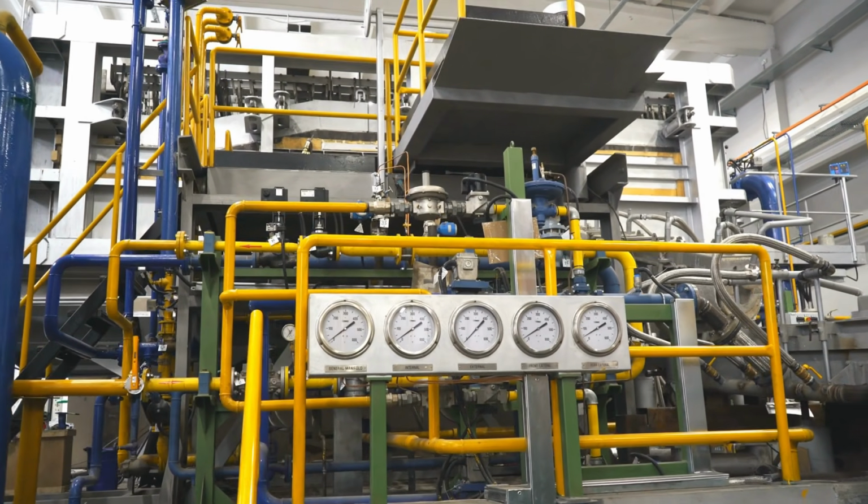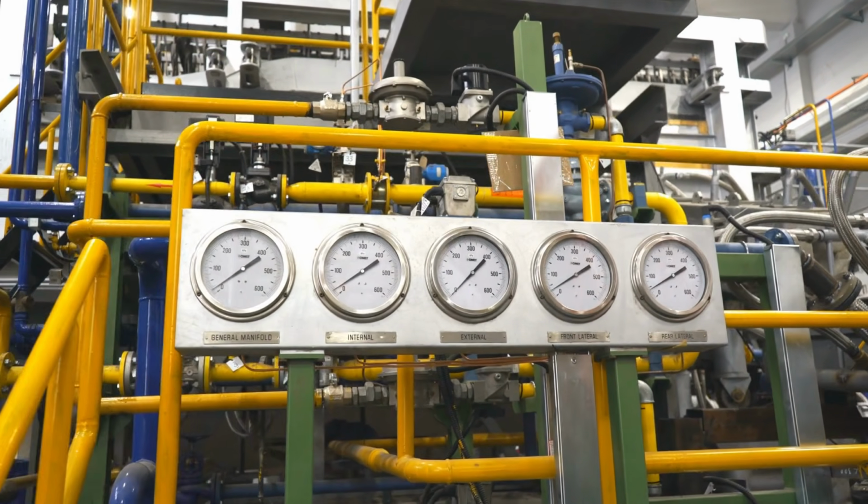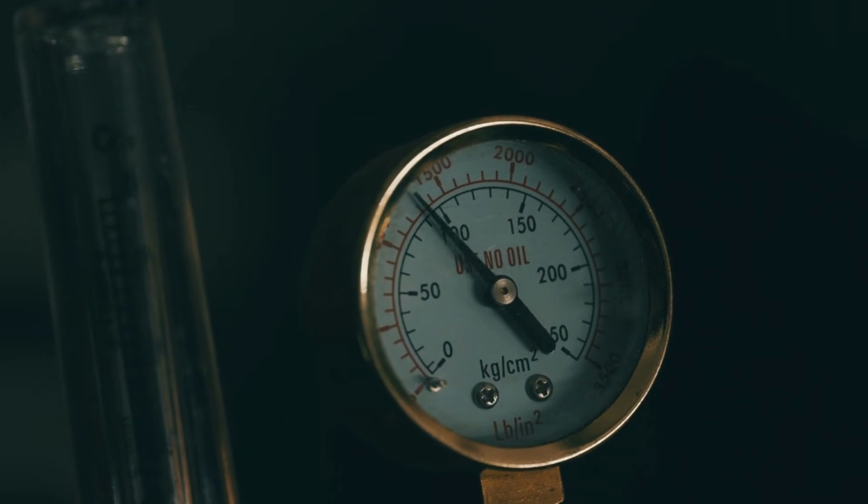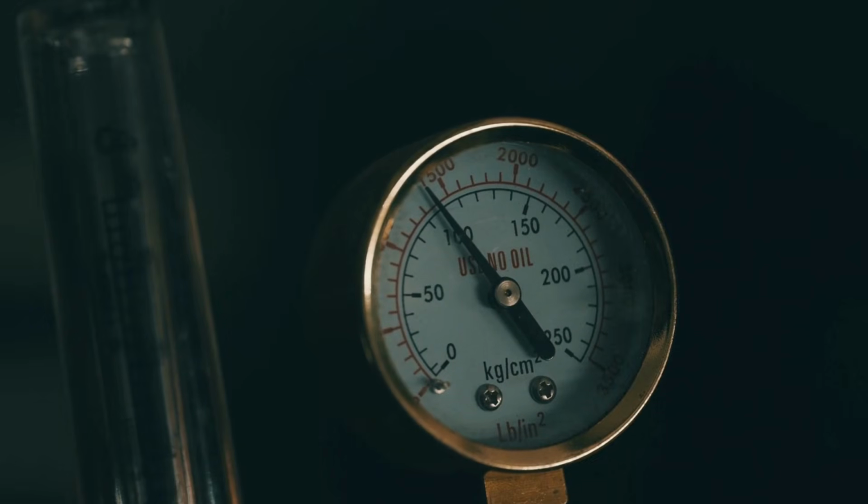So when we're moving away from the target, the system decides whether it's positive or negative and then makes a change in the opposite direction. For example, if we were monitoring speed and we were going too slow, that would be a negative error. So it would make a correction in the positive direction in order to increase our speed to match the target.